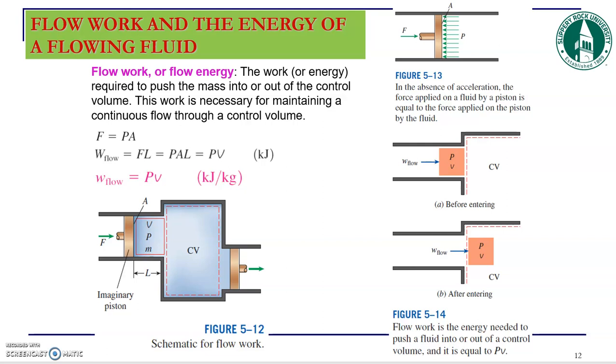So we have already talked about this in previous chapters, a term which is called basically flow work or flow energy. And what it means is basically how much energy is required to push a fluid inside the control volume, or basically take it out of the control volume. So that's basically called flow work or flow energy.